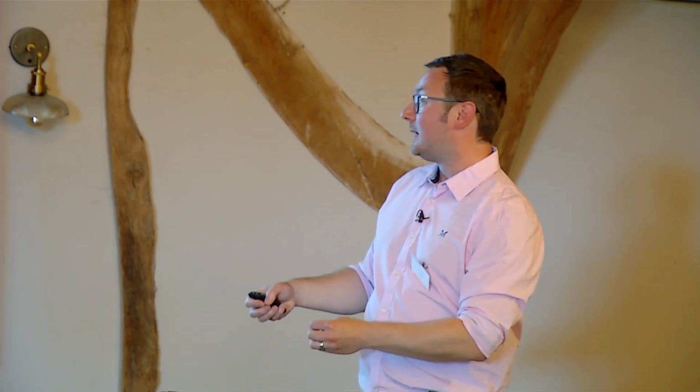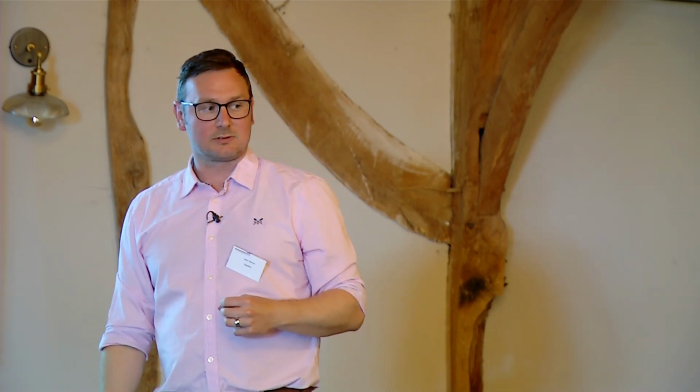So if you create a basement story, that basement should terminate into a protected stairway. And that's the point. Just because you have first floor means of escape windows and the ground floor, all of the rooms terminate into an access hallway, if you have a basement, then the entirety of the escape route should be a protected stairway itself, in which case you should upgrade the internal doors, upgrade the fire-resistant enclosures themselves. Any questions on those two?